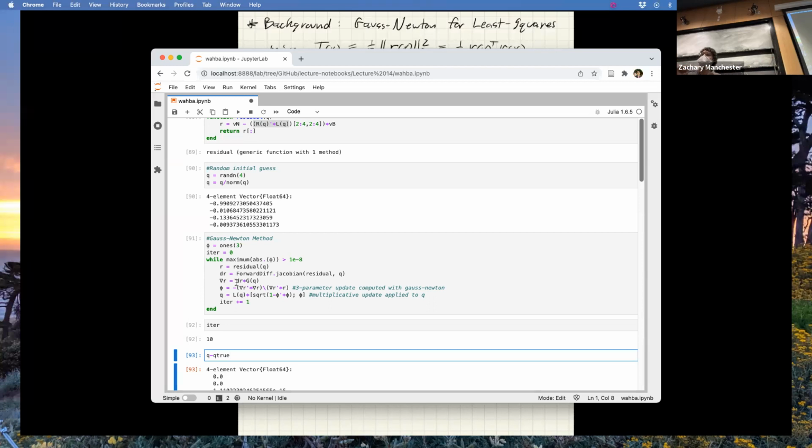The classic example of stupid behavior is the unwinding problem. Essentially, if you write down a cost function that only has a minimum at Q and not at minus Q, you can get into situations where the system will wrap around 2 pi for no reason. If you're epsilon away from minus Q, but your cost function says minus Q is bad and only Q is correct, you'll actually do a 2 pi rotation to get yourself to Q, which is just rotating around 360 for no reason, right? So that's something to worry about at some point, maybe.